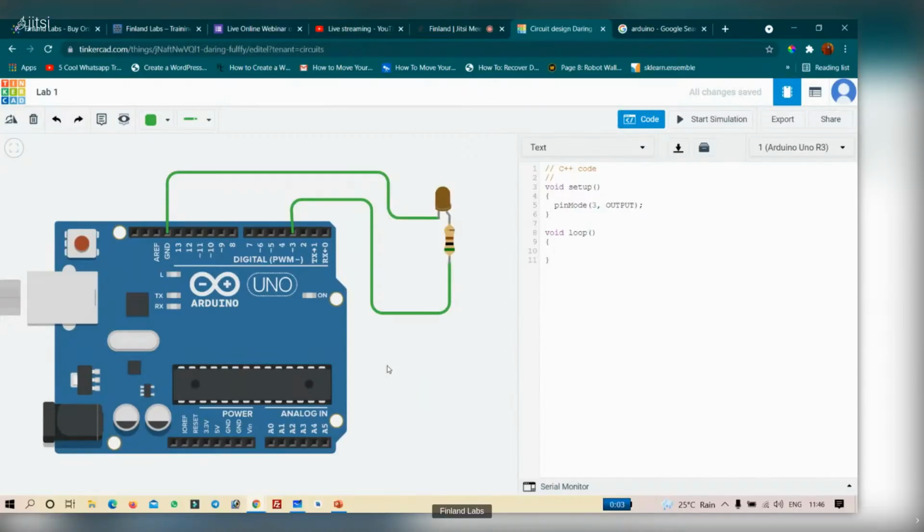No need, right? You can write in the loop, but actually it is not mandatory to write in the loop. It doesn't make sense to execute the same code again and again because it is not changing. So I will write in the setup only. I'll write here digitalWrite, here W is capital. DigitalWrite means that we are giving a digital output to my Arduino.